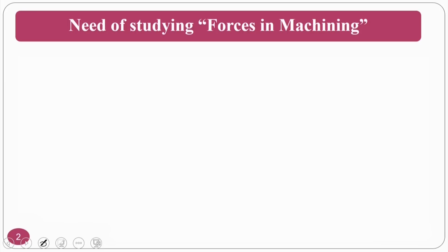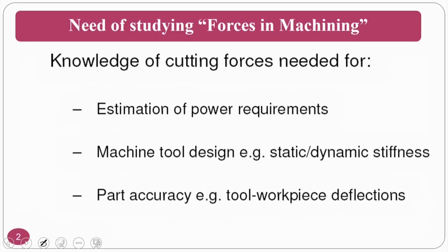So now we are moving to forces in machining. Normally we have seen the introduction to machining processes, so we deal with only the orthogonal case. First we should know the need for studying the forces in machining operations. The knowledge of cutting forces is required for estimating the power requirements. Normally power requirement is Fc into V.